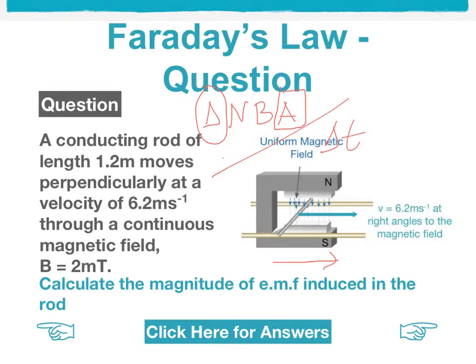What is the area? Well, it's drawing out a distance here of 6.2 meters in every second, in 1 second, right? And what is that area equal to? Well, the length of it is 1.2 meters, so it will be 1.2 times 6.2, which equals 7.4 meters squared in 1 second, right?